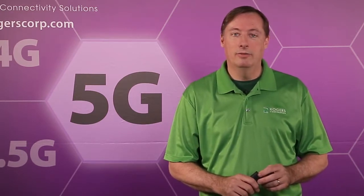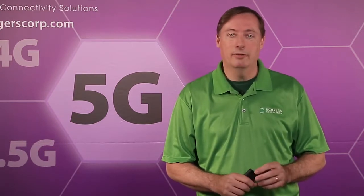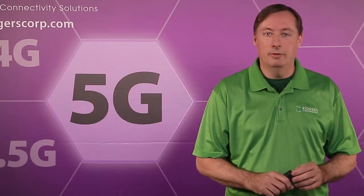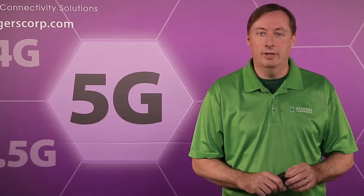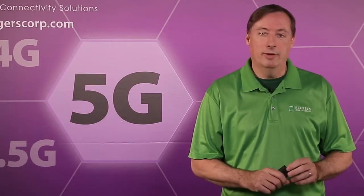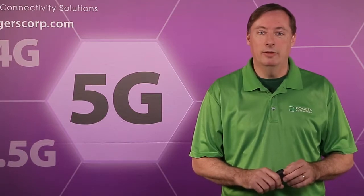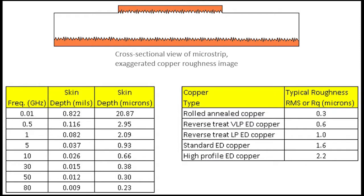The dielectric losses are more related to the dissipation factor of the substrate and/or the solder mask if that's involved. And then the conductor losses, there are many different variables there, but specifically I'm going to talk more about how copper surface roughness impacts conductor losses and ultimately has an effect on insertion loss. So with that, let me go ahead and show you a table of information that describes the introduction of this topic. Copper surface roughness will cause an increase to conductor loss, and also it has the ability to slow the phase velocity of a circuit.